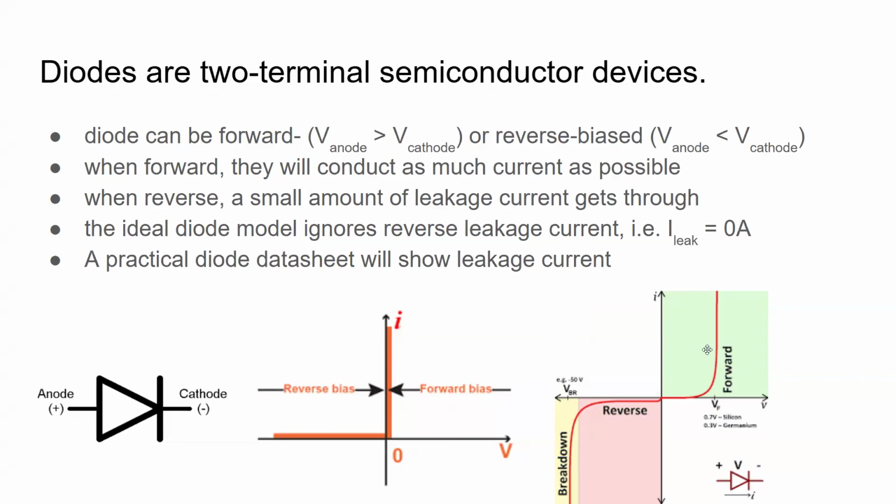Realistically, though, a diode characteristic curve might look like this on the right here, where it has some exponential increase, and it has some actual threshold voltage, right? This forward voltage drop, at which point we consider it to be forward biased. And then there's also this reverse bias case where it does physically break down and allow electrons to go through if there's sufficient negative voltage applied.